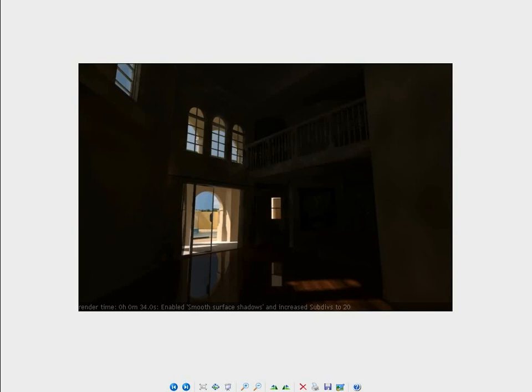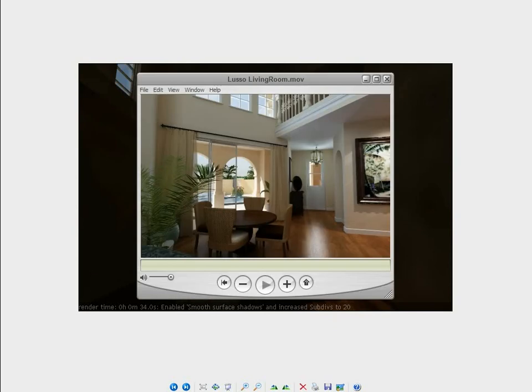So I'm finally ready to start adding light planes to all these openings. And basically anywhere outside light can come in, that's where I want to add these V-Ray light planes. The very first consideration I need to make is whether to place the lights just inside or just outside these openings. And what determines that is whether or not there's any objects that would interfere with the lights. I know that I can't allow any objects to intersect or touch the V-Ray light plane, because it can cause erratic lighting. So if there's any objects just inside these openings, such as curtains or drapes or any furniture, I might need to place the light outside.